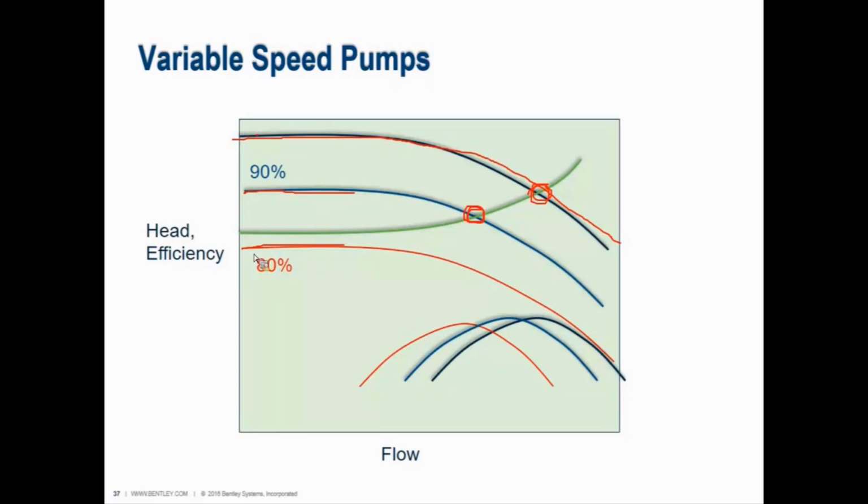So effectively what that tells us is you can run the pump with the variable speed drive from 83% to 100%. And to be honest, that's not really a range that's worth a variable speed drive and all of the hardware and everything else to get it to happen. So you would see things like this if you were running a system curve against a pump at different speeds and be able to see if it's really doing anything for you.